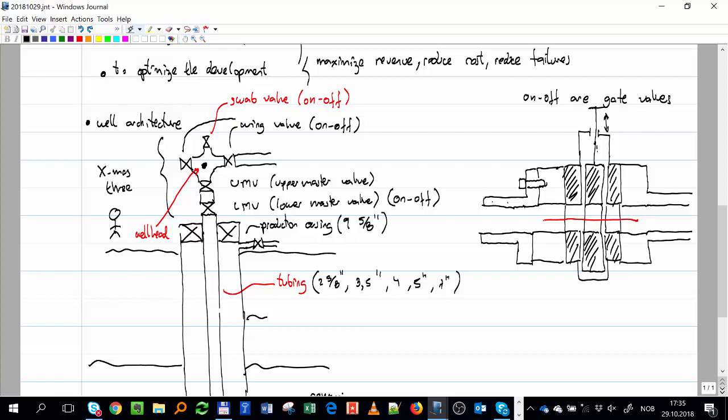Here I can make this pressure transducer. So to measure that pressure, I can close this valve, and then I can open this one, and it will measure my wellhead pressure. Let's put here: wing is to measure shut-in wellhead pressure.